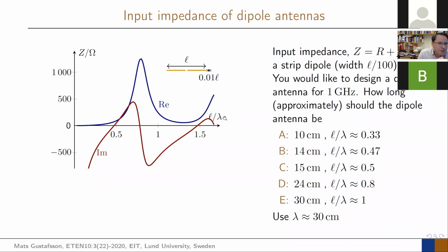And if we go back to this one, in these cases, so A, that means that you will be sitting at 0.33. You are down there. Not very good. Radiation resistance very low. The antenna is not matched. Very strong imaginary parts. If you go to B, you would go here. You are at the resonance of the antenna. You still have a radiation resistance.